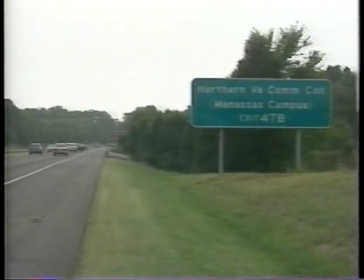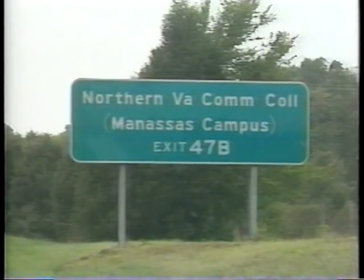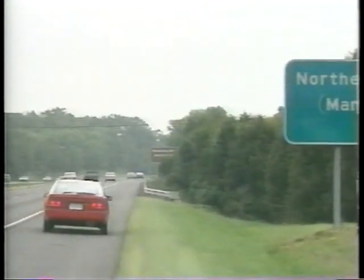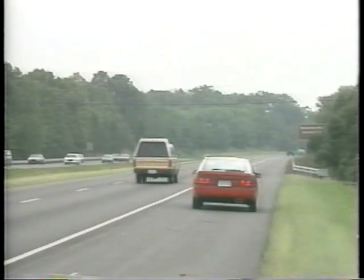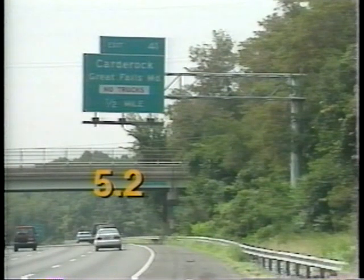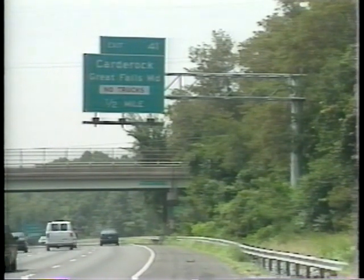All guide signs beside the road should be at least 2.1 meters above the pavement. There are no rigid criteria for lateral placement, but signs should not be closer than 60 centimeters from the edge of a surface suitable for normal or emergency use by vehicles. Overhead signs should be at least 5.2 meters above the pavement. Certain bridges and tunnels may require lower signs.